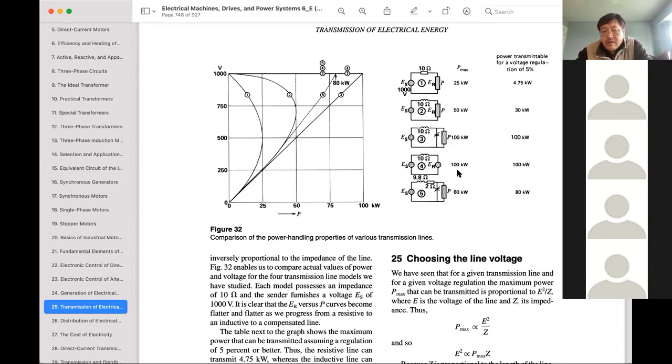So when your load increases, you increase the capacitor. When the load decreases, you decrease the capacitor. When the load decreases to a certain level, you completely cut off the capacitor. There's no need for a capacitor. And then if the load continues to decrease, you actually need to add an inductor. Well, that's amazing. You need an inductor.